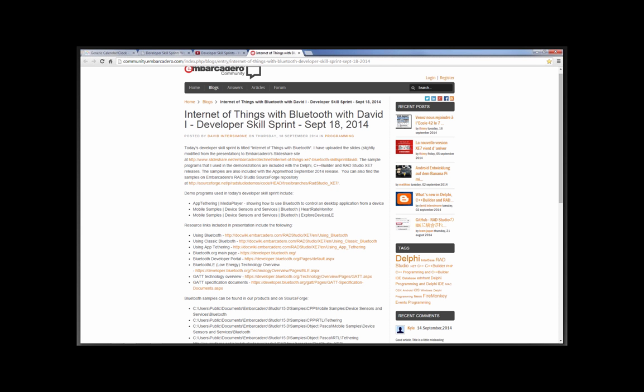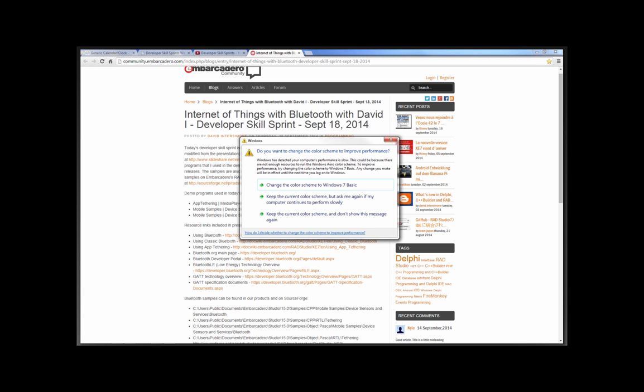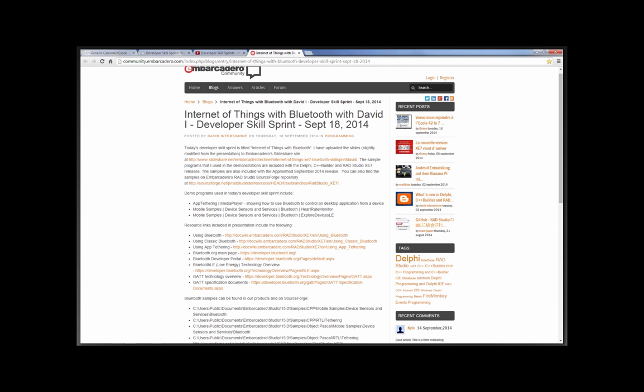You might also set the timeout a little longer if you're writing your own code. So if it's not finding them, they're either proprietary. Like I have a blood pressure cuff made by Health Labs, and it's discoverable. You can see it. There it is. You can see it, but I can't connect to it. It doesn't have a standard GATT protocol interface.